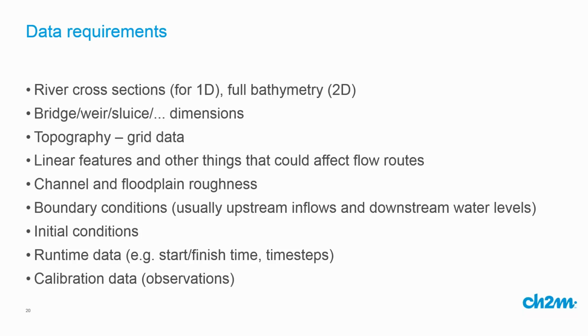So that's really good, the LiDAR data, but it's also useful to have linear features picked up separately. You may have lines along the top of the bank and there may be roads and embankments and things like that, and it's good to have those as polylines or polygons, not just as gridded data. We need to assign a roughness value both to the channel and to the floodplain.